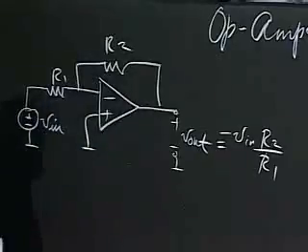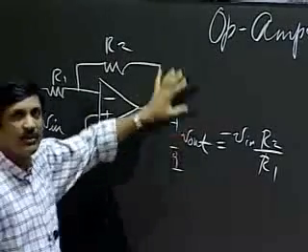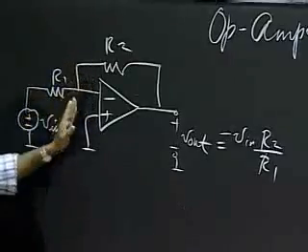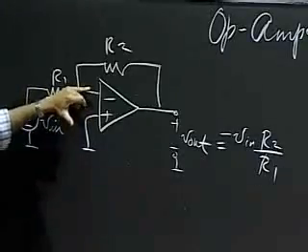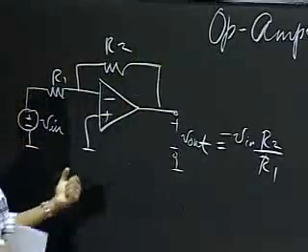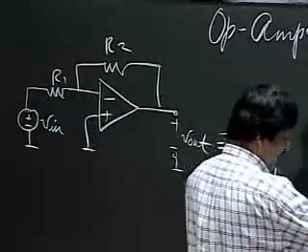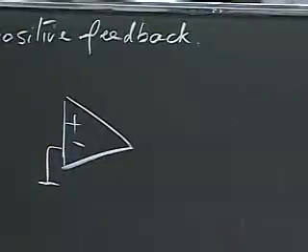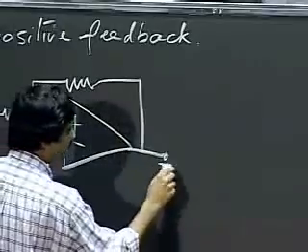So this is a negative feedback circuit because it's always fun to do the intuition thing and say that, look, if this voltage tends to go more positive than I care, then this negative input goes more positive than I care. If that goes more positive, then the negative input V minus becomes more positive than the plus input, which yanks the output down. Okay, so there's a nice counteracting force that keeps the output stable. So let's look at this circuit. Being curious engineers, let's look at the opposite here, where I give myself some positive feedback in this op-amp.